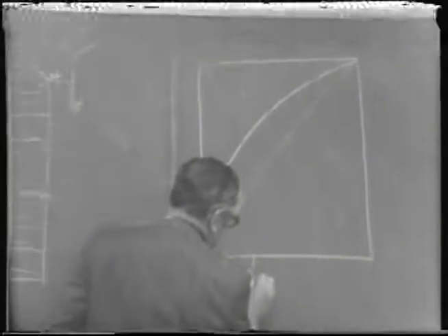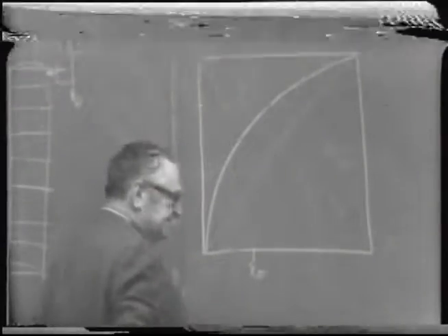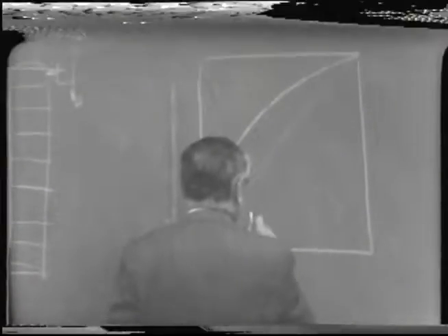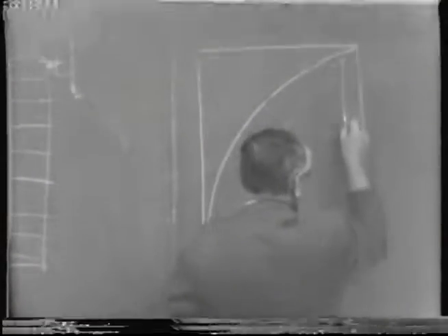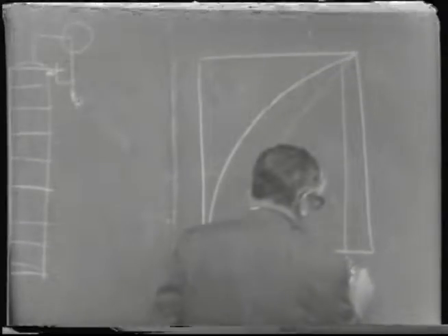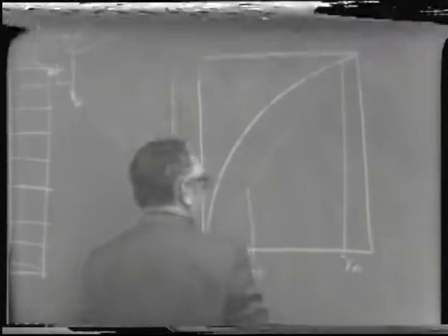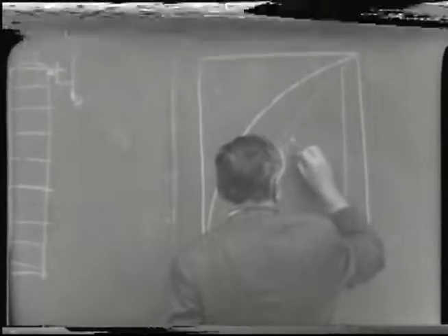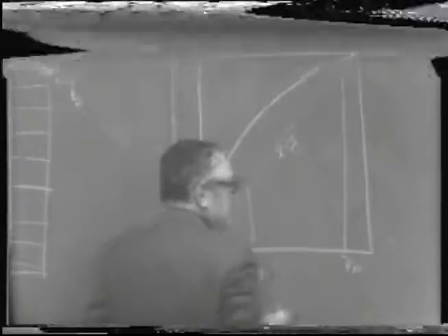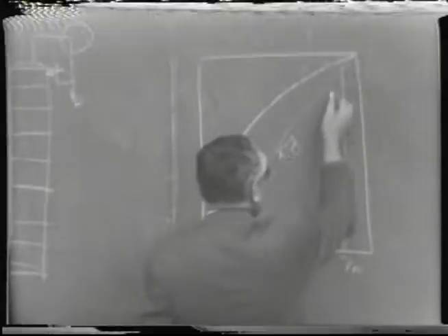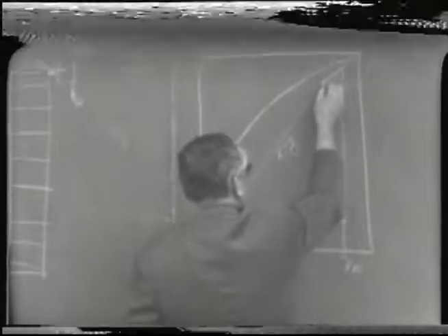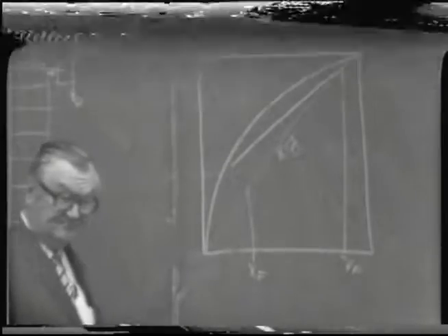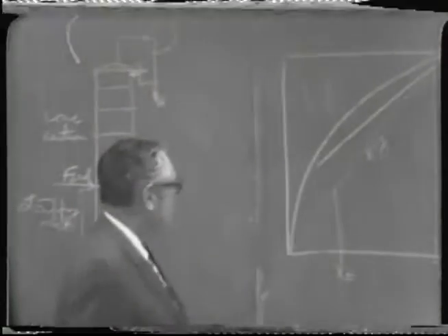If we have a certain feed mixture indicated by X sub F, we will find that for a given product composition in this rectifying section, we have an operating line which does not coincide with the diagonal, but it intersects the diagonal at a value of X sub P and has a slope which is something less than 1, less than ideal.